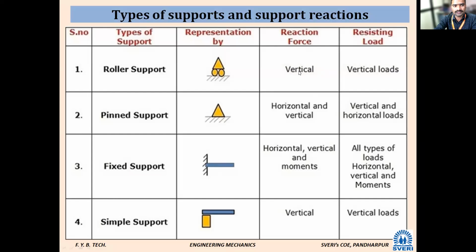Next, the third one is pinned support. Pinned is also called hinged. This is how you have to show the hinged connection. What reactions will develop for the pinned connection? Two. What are those? One is horizontal and one more is vertical.